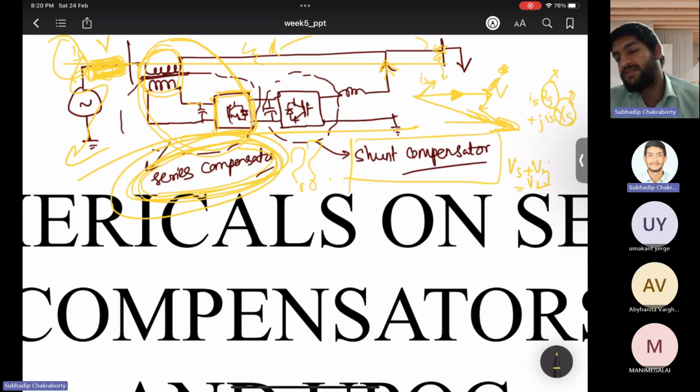Distribution systems have high impedance in the lines because they are at the far end of the power system. So high resistance or feeder drops may be there, and that's why sag and swell phenomena are very common. But at the load, you don't want such abnormalities. So you connect the series compensator in those conditions such that your load receives good voltages. So this is good for such applications in the distribution network.